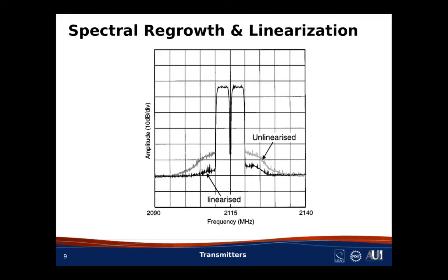But the power amplifier is not linear, and that has resulted in some spreading of the power, and this has happened across at least 30 MHz of bandwidth in this example, whereas the original 2 signals together were limited to 10 MHz. This is an example of spectral regrowth. Note that the spreading of power will be a problem for a third signal that is either sent or received in one of the 5 MHz channels where this additional power has fallen.